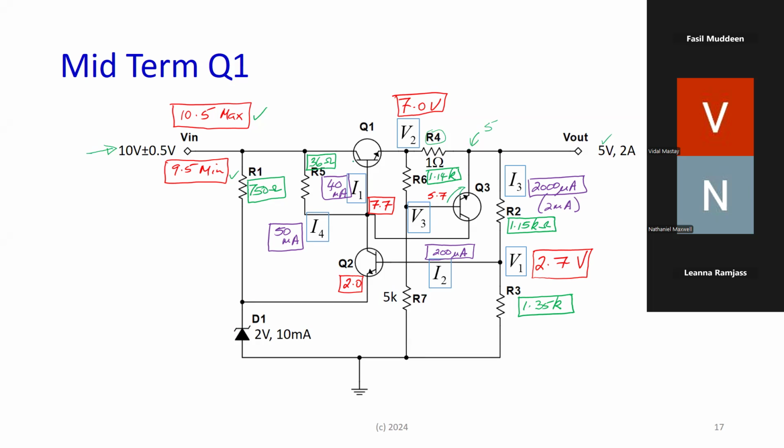Right. And then once you had that, then the currents themselves, I gave you the idle currents, and everything else was just a question of using the currents and the HFE or the beta for the particular transistor. So you'll follow it through and see what I have.